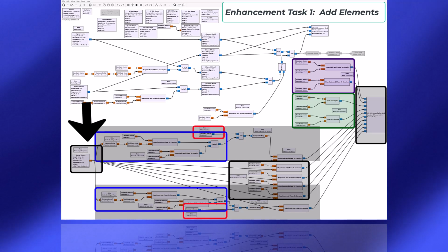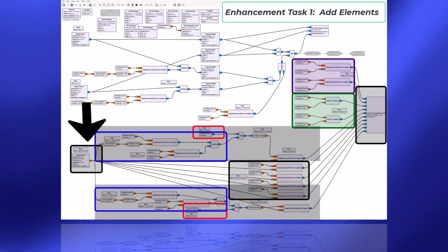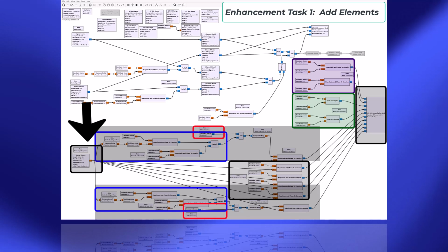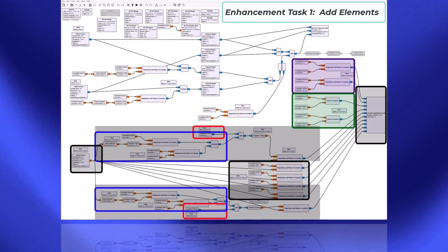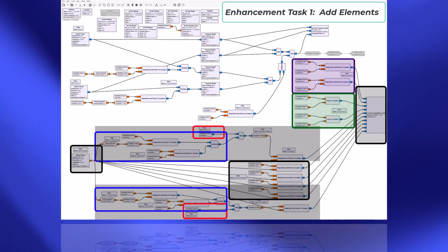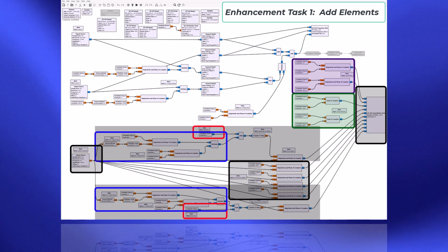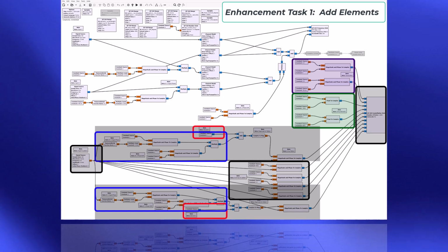I've multiplied it by pi so that the value of that cosine function that is output from the signal source varies between negative pi and positive pi. And we can convert this to degrees if we want to, or we can leave it in radians and use that as the angle for calculating the array pattern.